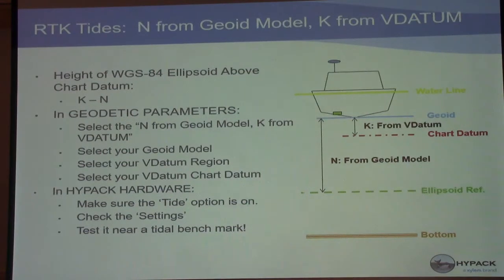And then, like I mentioned before, if you load up a geoid model, but the separation in your area is different, you can load up the VDatum files.